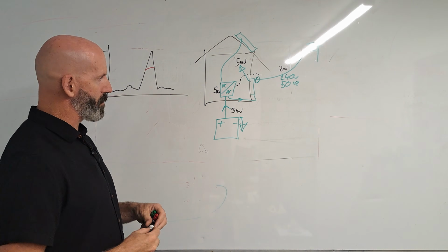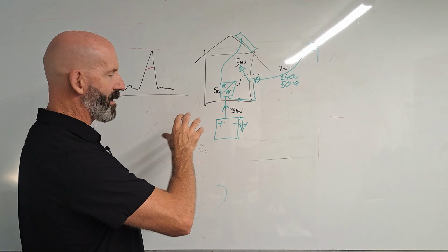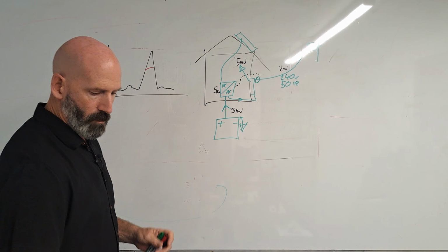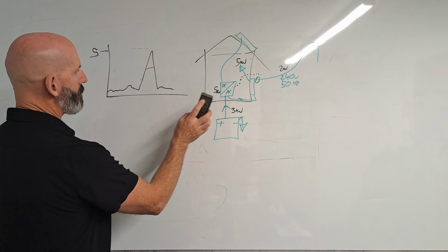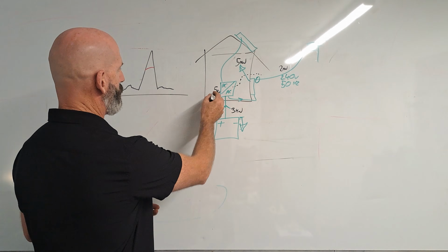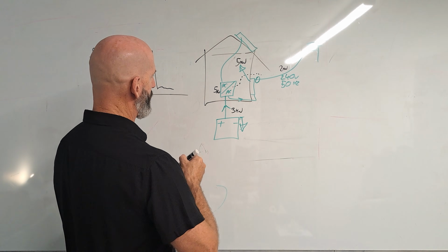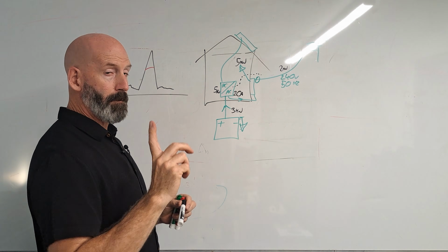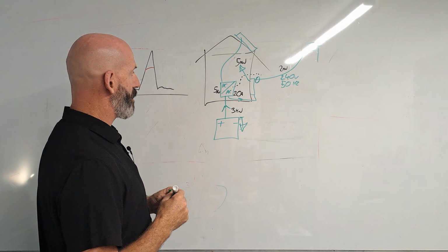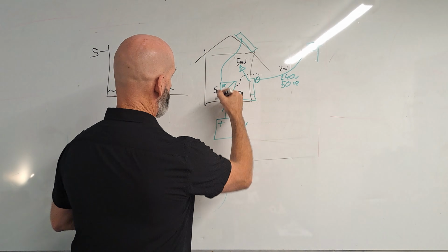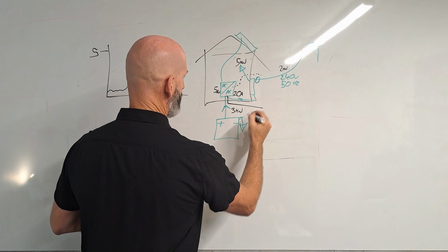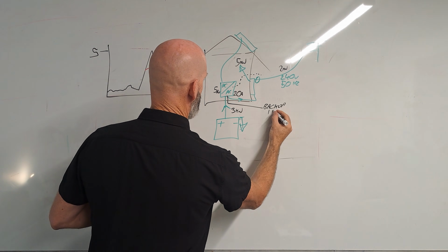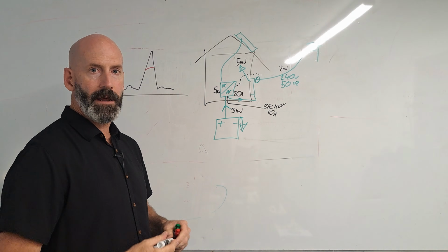Now, obviously it's not having a logical conversation. This is all electronics that does this. But this is where hybrid systems work. So this is also why you've got your 5 kilowatt inverter here. Under normal operations, it can give you 20 amps. It has a backup function for when the grid goes down, and you find that backup function on that second line, backup might only be 10 amps. Why is that?